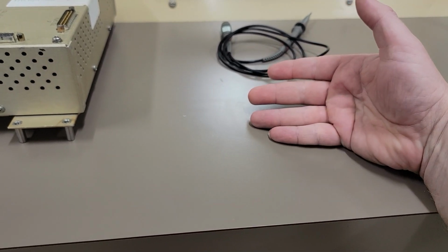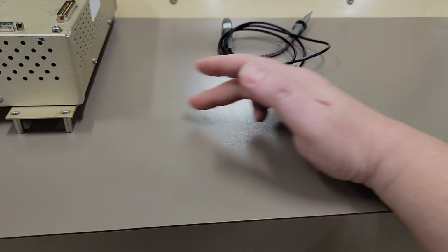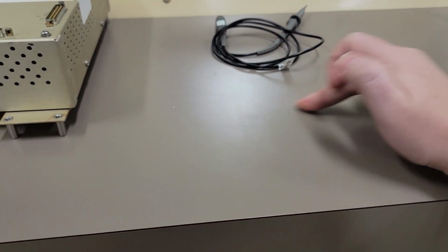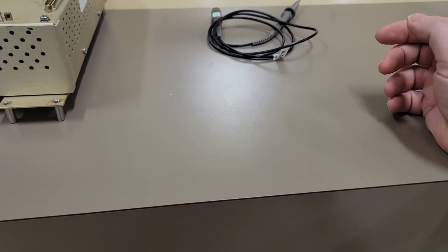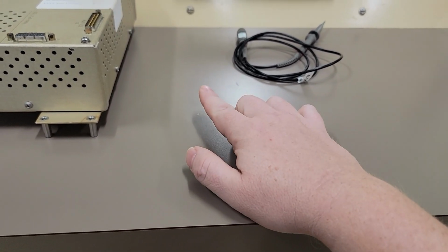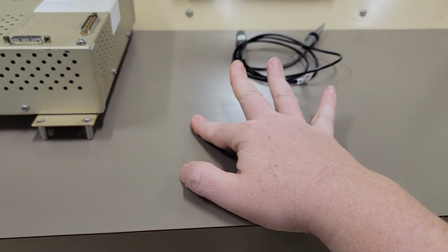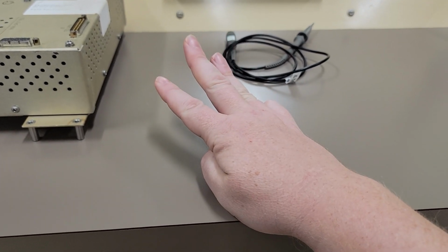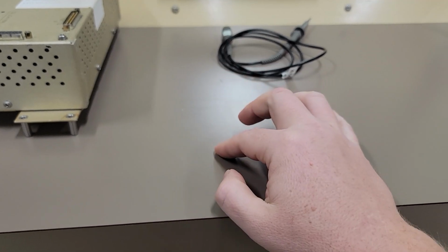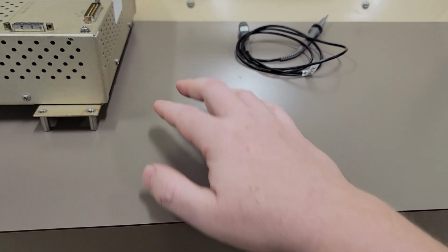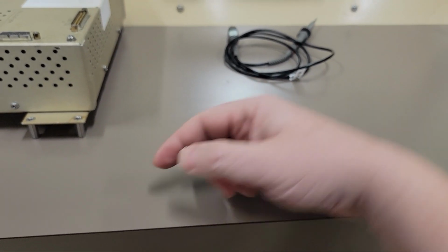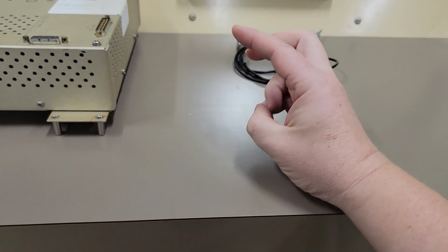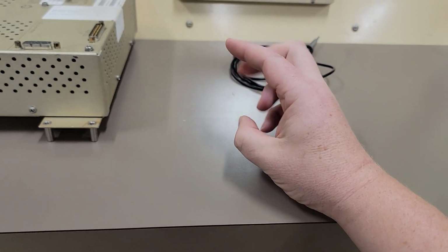Just to throw a number out there, say this amplitude was a 3-volt peak. The bottom amplitude would be at a negative 3-volt peak, if that makes sense. What you actually do is you take your red signal for your video and send it through 3 different comparators, and thus you have 3 outputs of red the same as the input, and 3 inverted outputs of red. Then you do the same thing for the green, and the same thing for the blue. Then you do the same thing for your horizontal and vertical sync.